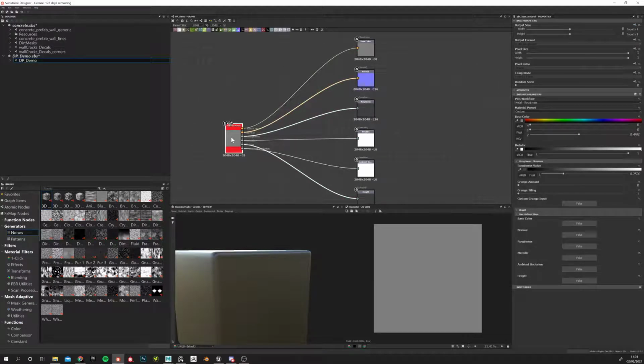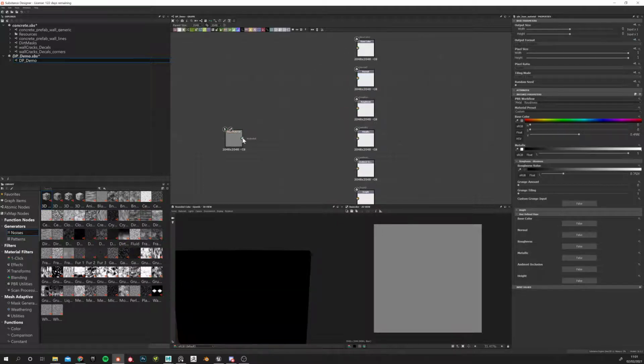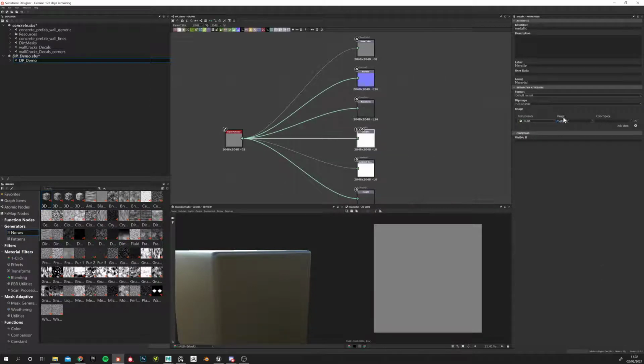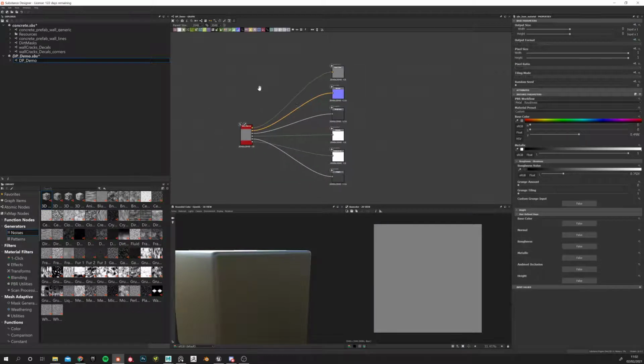So 1 is with all the connections individually. 2 is material; you connect with the material. And then 3 is compact connection. Instead of going one by one, you can do that, and it's clever enough to understand because these things have been tagged already with the components and the usage, and you've got the naming convention as well. So if you want to do that temporarily, you can press 3, make the connection, and then press 1. Select this guy, press 1, and you're going back to the way 1. Or you can just do what I did, okay?